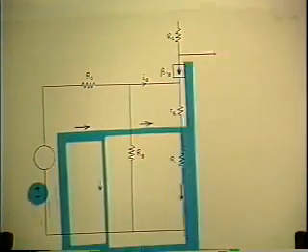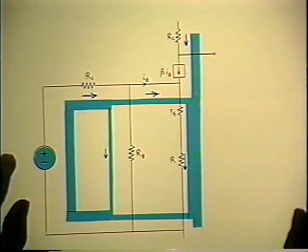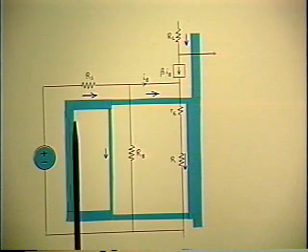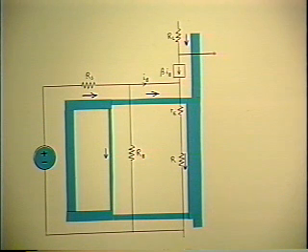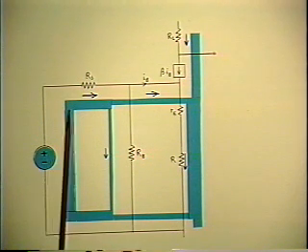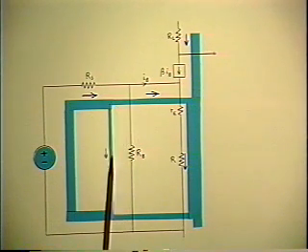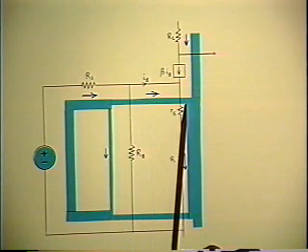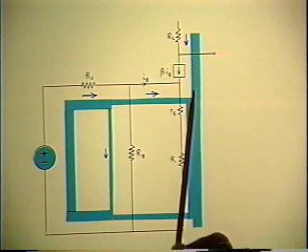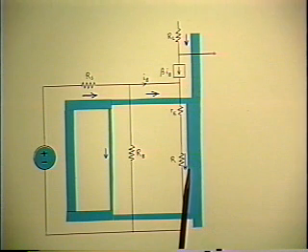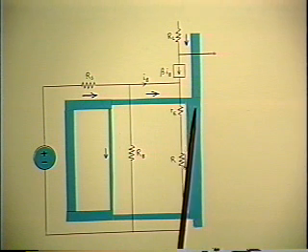Okay. Here's an overlay which is intended to suggest, in a very qualitative sort of way, the strength of the current that exists in the various branches. The width of the trace represents how big the current is. So what happens is V1 drives a current into RS, which splits. It's a current divider. Some of it gets lost in RB, some of it goes into the base, where it gets multiplied by beta in coming out the collector. And the emitter current is the sum of the base and collector currents. 1 plus beta times IB. In this qualitative sketch, of course, the value of beta is about 2.